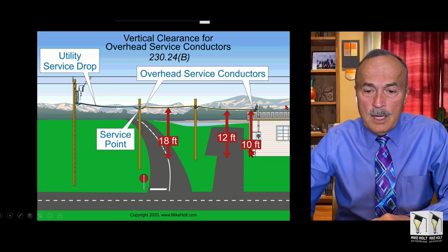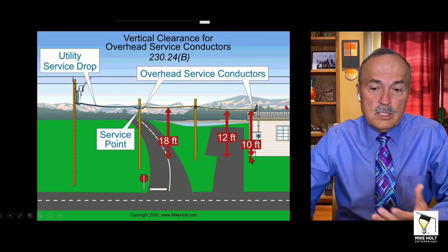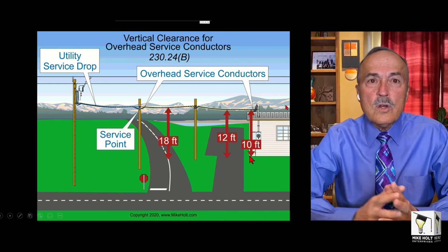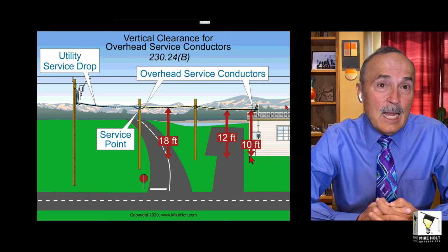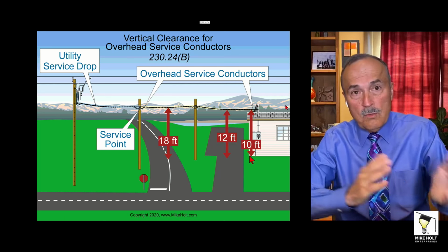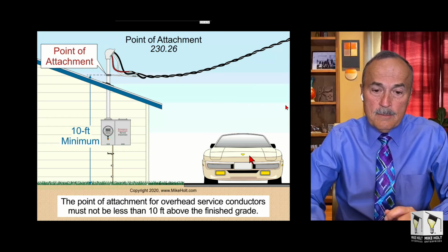And if you have just simply from grade, not a driveway, the overhead service conductors are going to be 10 feet. Highly unlikely that you're installing overhead service conductors. So let's make sure when we have a question, we know what we're talking about.